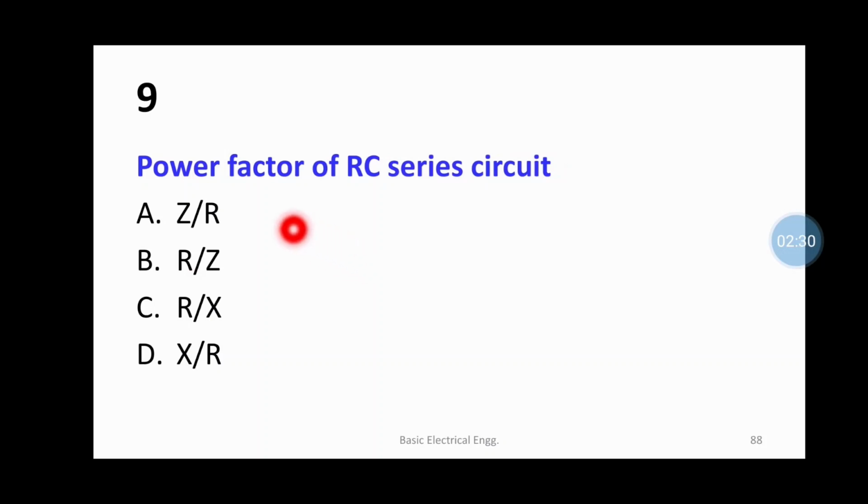Question number 9. Power factor of RC circuit. If you inspect the impedance triangle of RC circuit, it will be similar to RLC circuit and RL circuit. So therefore, the power factor of RC circuit also will be R by Z. Please do select option B.